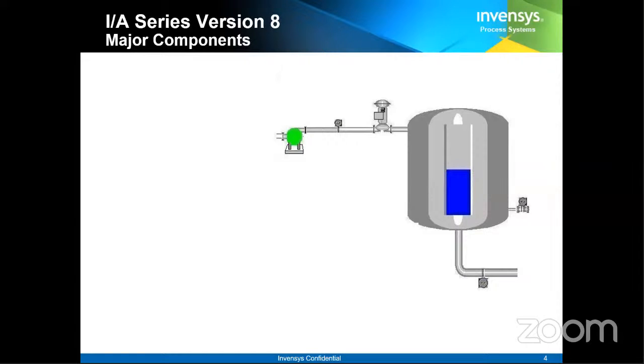From your basic engineering studies in process control and its applications, you might have studied that discrete control is not always able to fulfill our purpose. In this level tank, let us say the level can change from 0 to 100 feet, and I want to maintain the level exactly at 75 feet. A discrete control loop will definitely not help me, so in that case we use a continuous control loop.